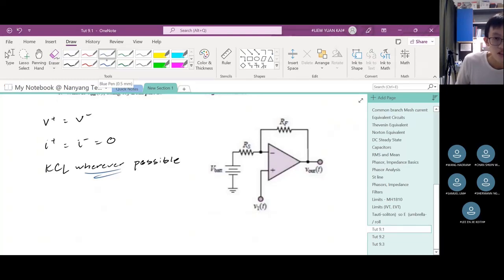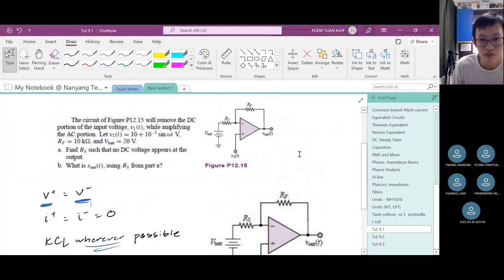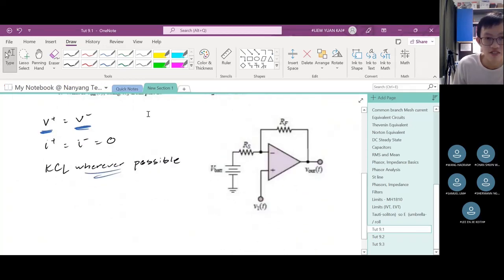So we know for a fact that V plus is equal to V minus, correct? Let us look at the diagram first. I just copied this from up here. It's just an enlarged photo of the figure that they provided. Now, take a look at the terminals. The easier terminal to analyze would be this one, because there's not much connected to it. The only thing connected to it is this V1 source. So we know that V plus, this voltage, is equal to V1, because this entire thing is a node. Ask yourself, is there any device inside here? No. So it's one node voltage.